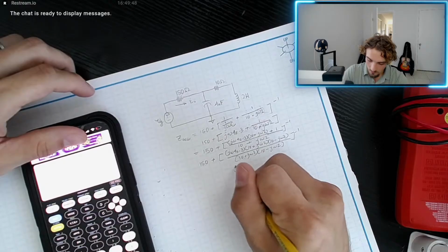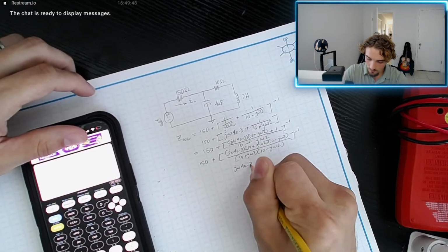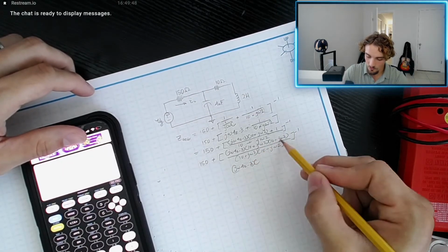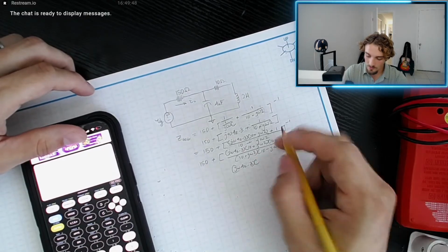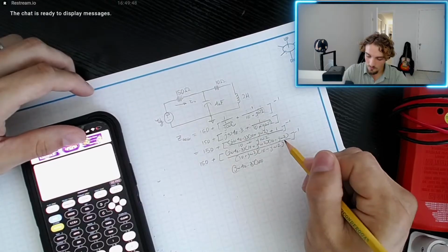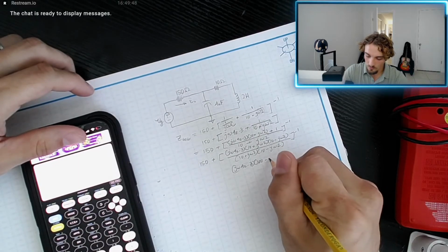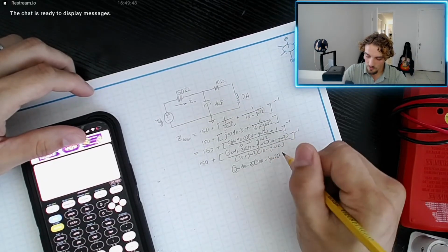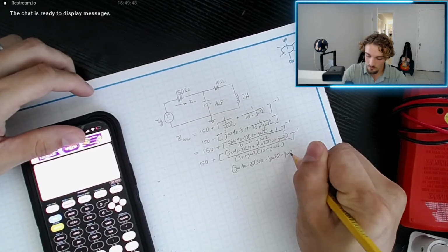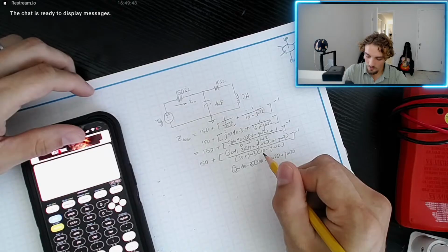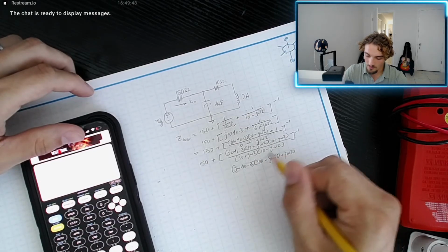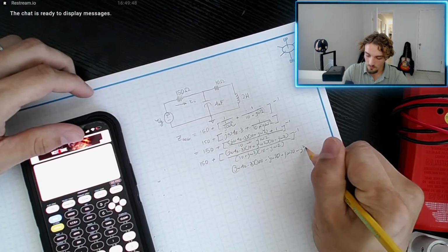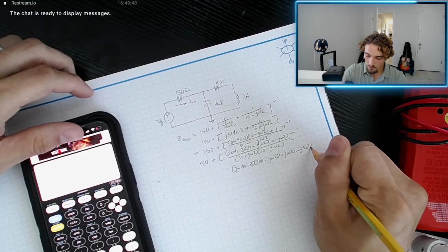So we'll say multiplied by, so we'll do a distribution here, and then we'll multiply this in later. 10 times 10, 100. 10 times negative j omega 2 minus j omega 20. j omega 2 positive, plus j omega 20. And then j omega 2 multiplied by negative j omega 2 is a negative j squared omega squared 4.